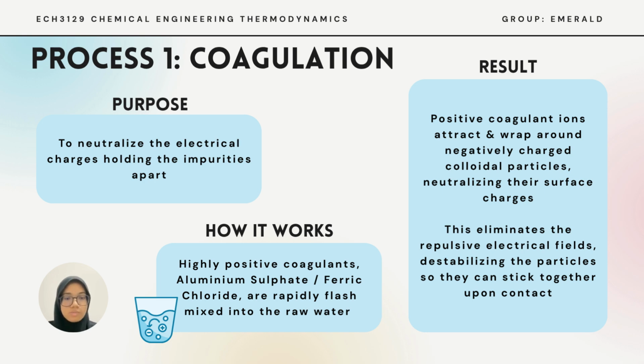As a result, these positive coagulant ions attract and wrap around the negatively charged colloidal particles. By neutralizing their surface charge, we eliminate the repulsive electrical fields, destabilizing the particles so they can finally stick together upon contact.